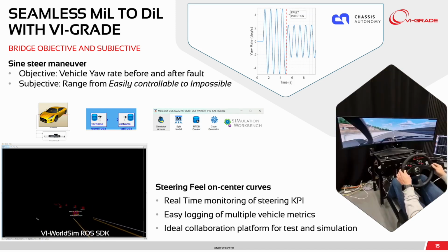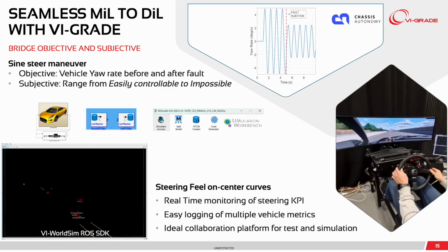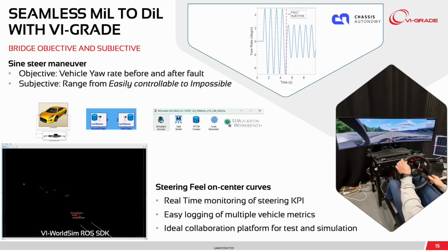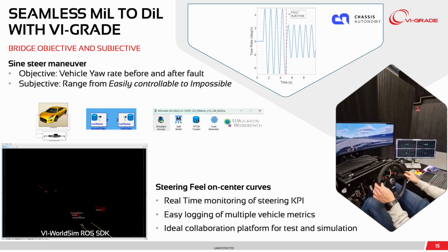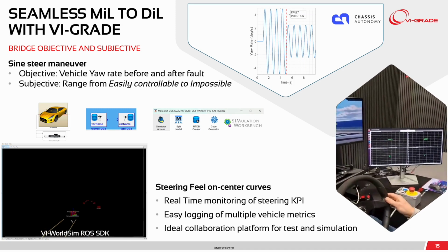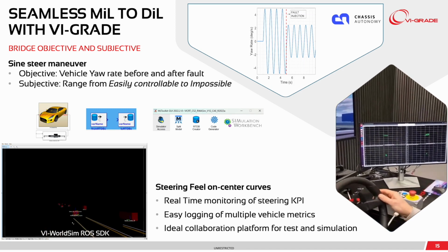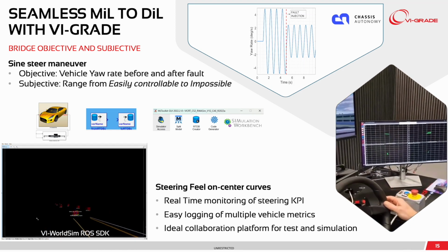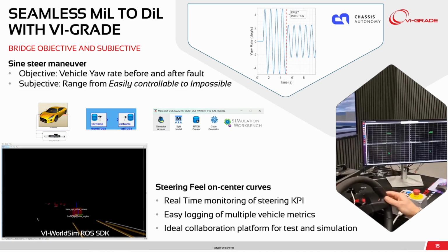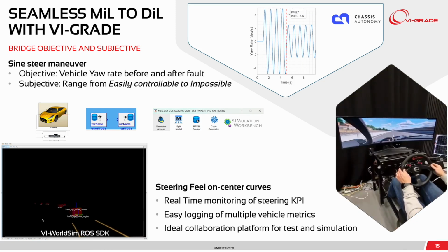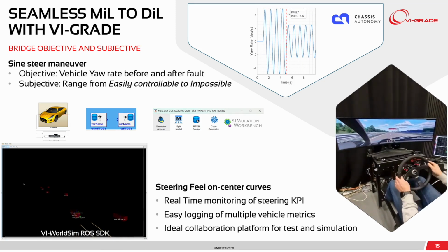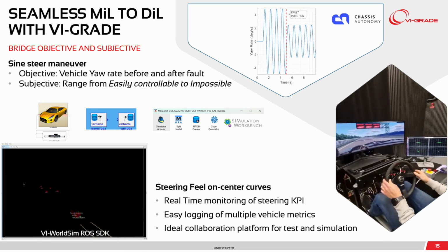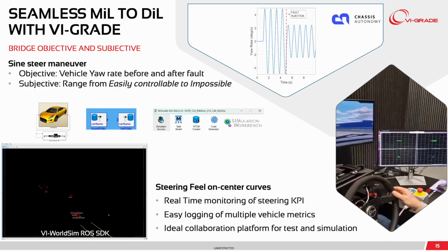And then how do you take it to a simulator? It's pretty easy. You take your system model, replace the interfaces with something known as real-time database blocks. So you're making the system model simulator ready. And then you compile your model into the driving simulator. So this gives you a pretty seamless process, in my opinion. And you can see the driving simulator in action here.